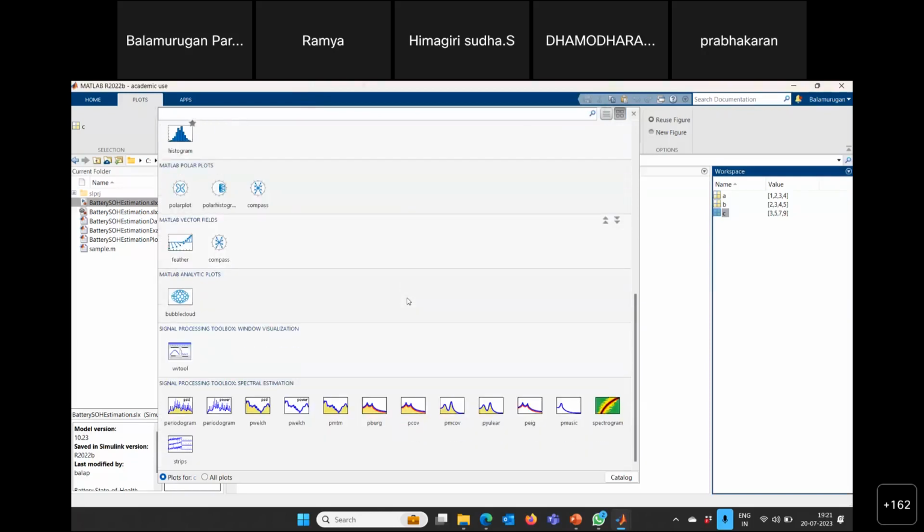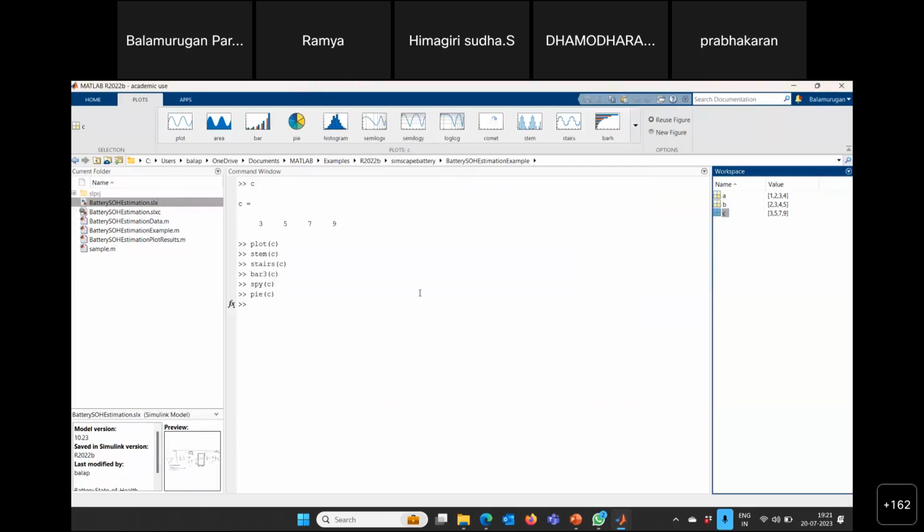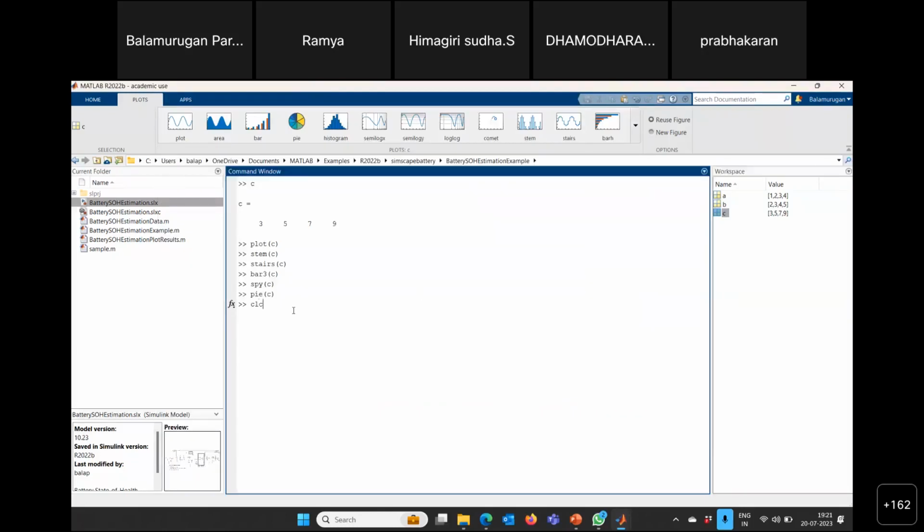Suppose if I use a transfer function, then I can find the control parameters over here. Let us see. Let me define a system. S is equal to TF. TF is a command which indicates that the argument passed within this bracket is a transfer function, right? Here again, if it is a transfer function, I'm just going to give only the coefficients of my numerator and the denominator polynomials. So let us consider my transfer function is 1 by 1 plus s.